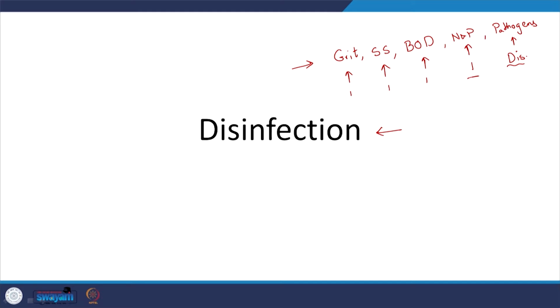So some treatment plants, especially the older ones, will not have nitrogen and phosphorus removal, but then you can look at upgrading them. So in the context of disinfection, we have different ways to go about it. Some are cheaper, but they are not effective against all kinds of pathogens. Some are relatively more effective, but they are relatively expensive, and greater technological know-how is required to be able to maintain the system. So it's a balance between what you are trying to achieve.